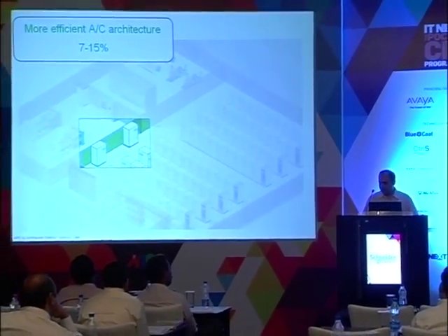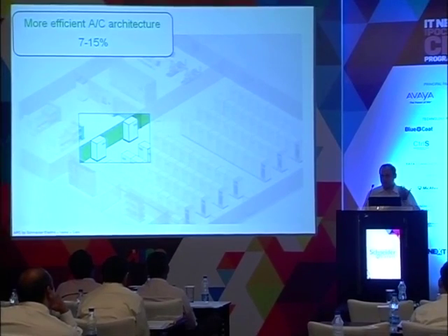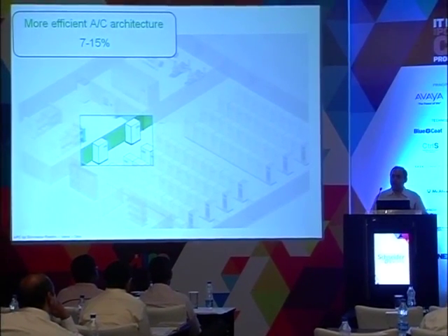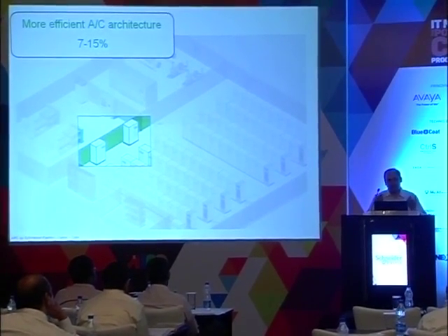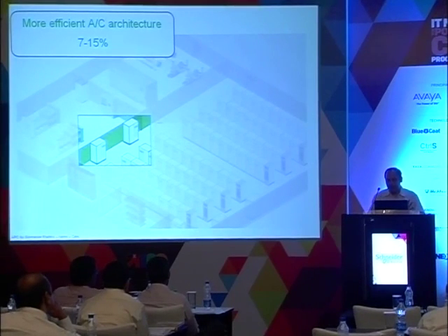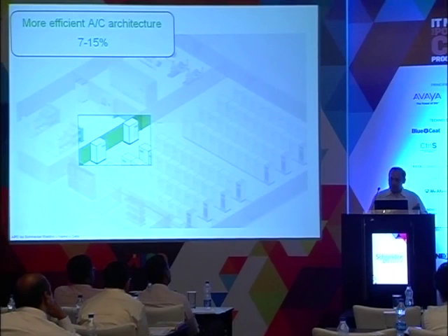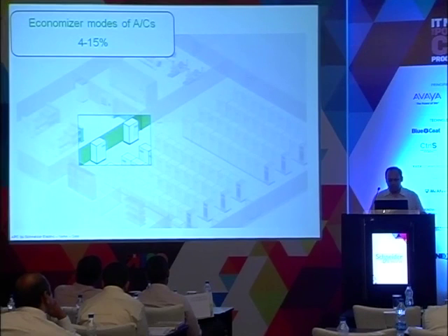More efficient air conditioning architectures increase the set points, right? So typically, it should always be more than 25-26 degrees Celsius your set point, ideally speaking. Again, you need to ensure that there are no short circuit paths created in your data center, because otherwise, by trying this improvement methodology, you may start getting alarms on some IT equipment. So we need to solve that airflow problem first, then target the set point problem, and then you can very easily increase set point temperatures even up to 27-28 degrees Celsius.